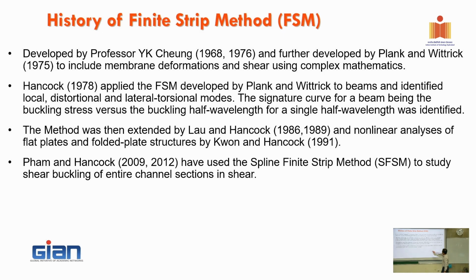However, from this work, we found that you need to take into account the flange and lip, the whole section carries the shear as well, not just the web panel. So that's why that paper came up, and it gave about 15% or 20% more than if we just treat it as a single web member.